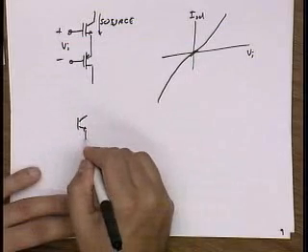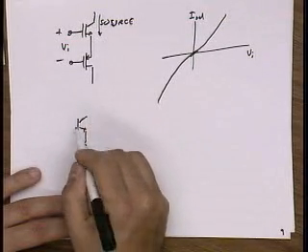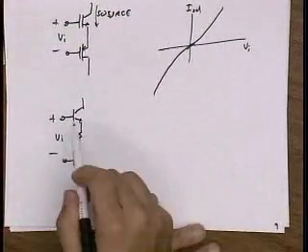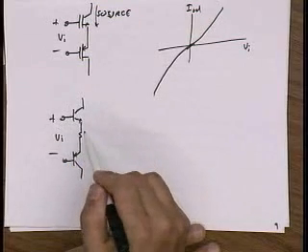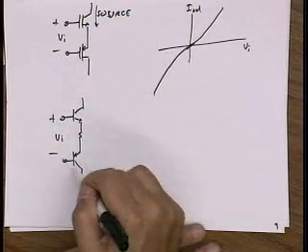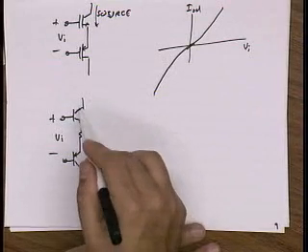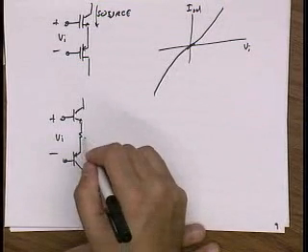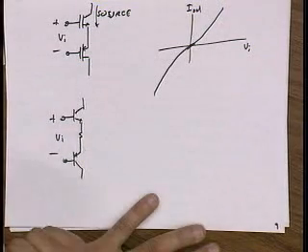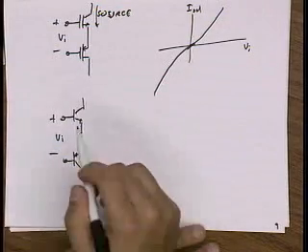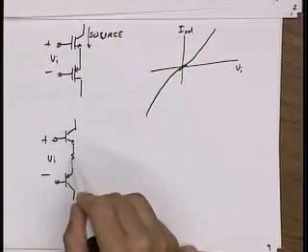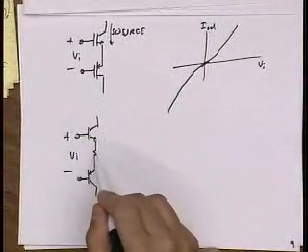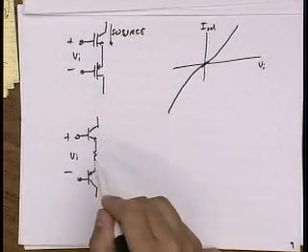So getting back to your question, similar operation, right? As the input gets bigger and bigger, this device remains off, this device shuts off, and all the current just comes from this device. So you might ask, going back to the question, what if we didn't have this resistor here? Actually, I guess I was wrong. If we didn't have this resistor here, the circuit would still work fine. Even without this resistor, it would still be class AB.